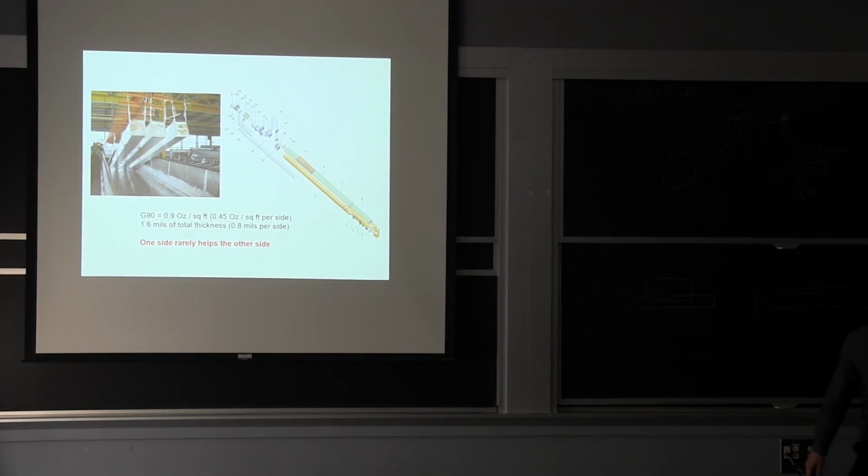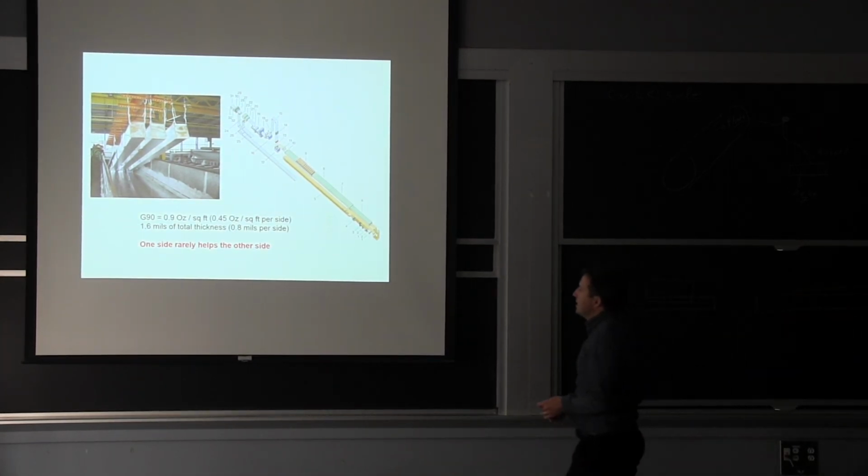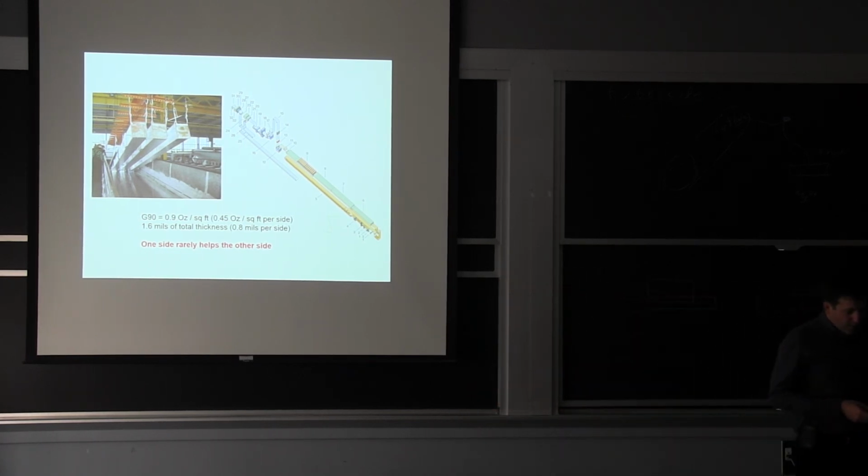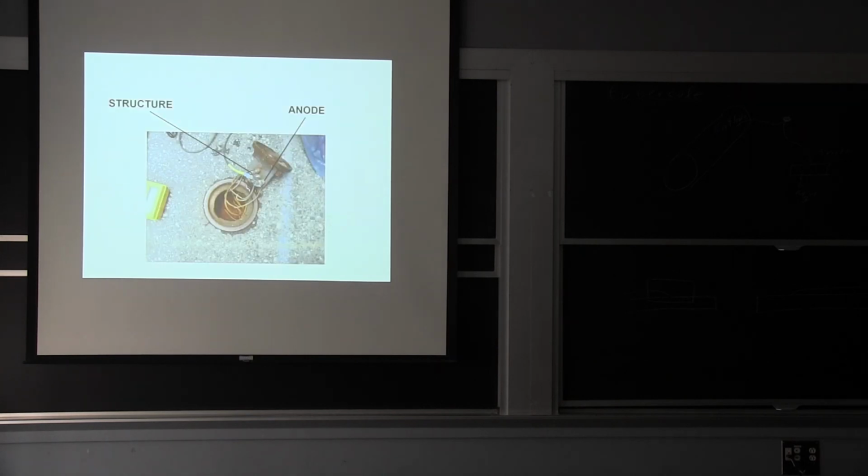So the hot dip galvanizing, again, is you clean the steel and you drop it. There are a lot of ins and outs in terms of if you want to protect the inside of a tubular structure, which is very typical. You need to have access holes into it so the liquid can penetrate and get out on the other end. It's one of the biggest issues because you don't want to have too much zinc on the inside. If you're making a tubular structure and you have a lot of zinc on the inside, it can affect your mechanical properties. You can start cracking that zinc, and then it gets to the primary structure. So that's a big issue.